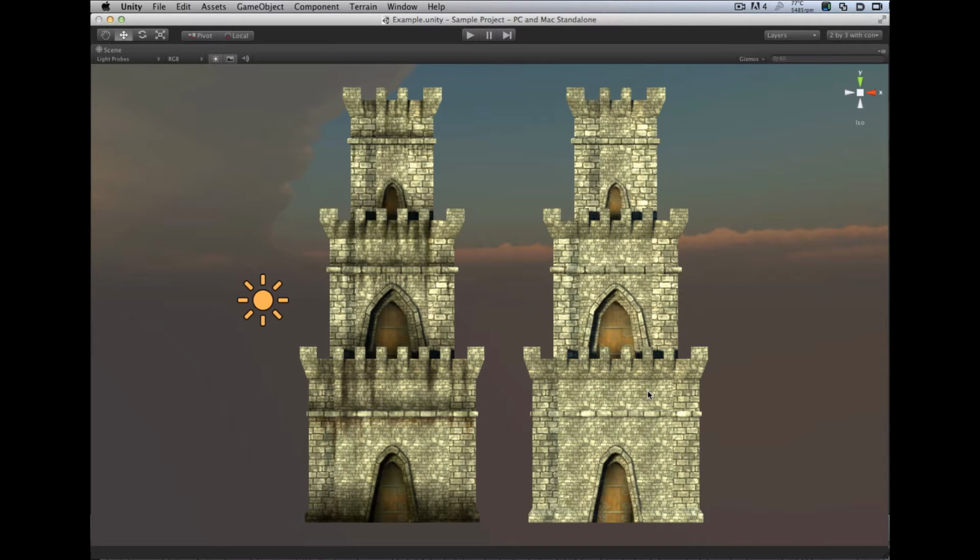But of course we really need to be able to use tiling textures, because otherwise we would either have to sacrifice a lot of resolution and wind up with a lot less detail on our model, or perhaps use a lot more texture memory to use enormous textures, or have to use more memory by using multiple textures and also incur additional draw calls. And all of this is going to negatively impact performance. So we want to be able to stick with a model that for the most part just uses tiling textures, but we want to be able to mask all of the monotonous repetition of the tiling texture while also adding character to the model. And that's what Grungifier helps us do.